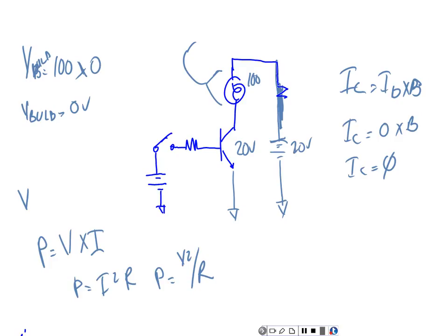That's an open switch, right? But what we're doing is using this little tiny switch, because all it's got to do is drop this voltage right here, by the current that needs to flow through that resistor. And what determines the size of a switch? Two things determine the size of a switch. The current. Switches do not do watts. So amps, current.